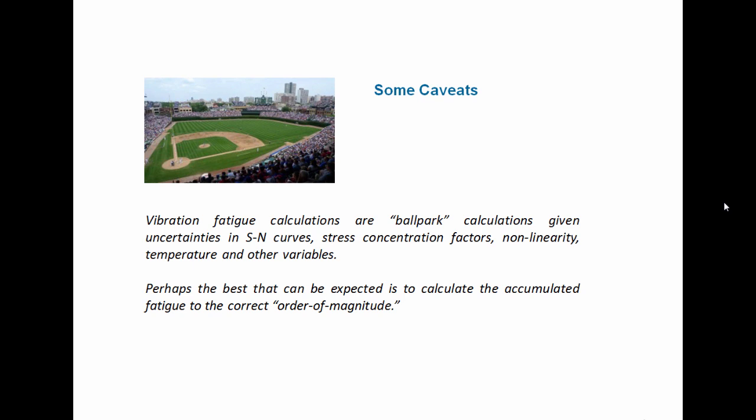But these curves, it's very complicated to get really good SN curves because there's so many different factors. There's stress concentration factors, nonlinearity, there can be temperature, humidity, salt fog.